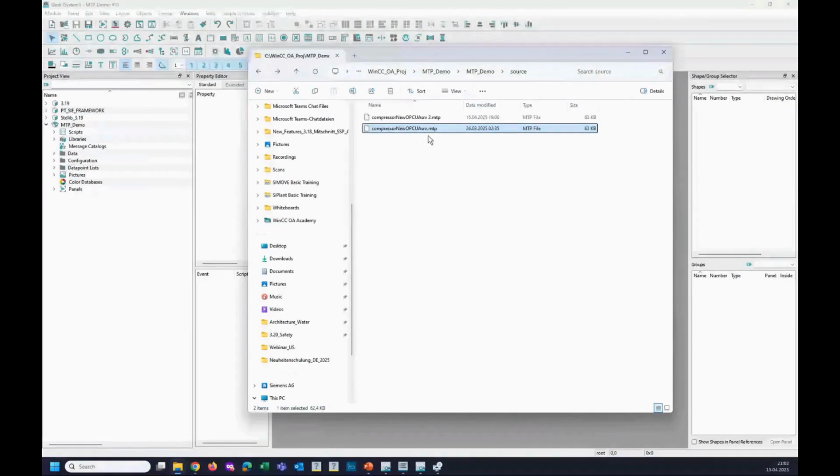The package contains the content of the tags from the machine, but not only that, also the configuration, of course, because it was engineered maybe with TIA Portal or other means. Also, there is information about which driver to use. In this case, it is the OPC UA, which we are using here. And also, it will have some information about the graphics.